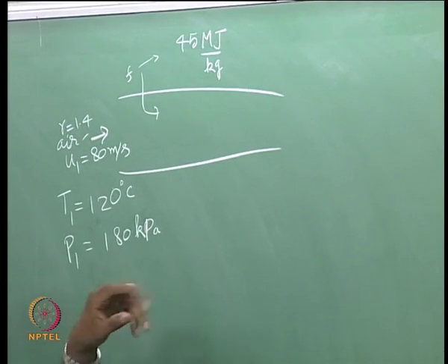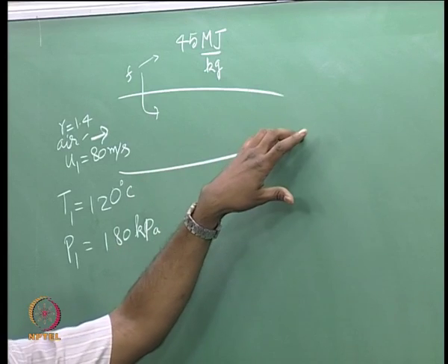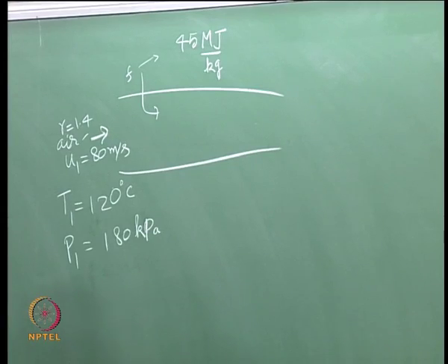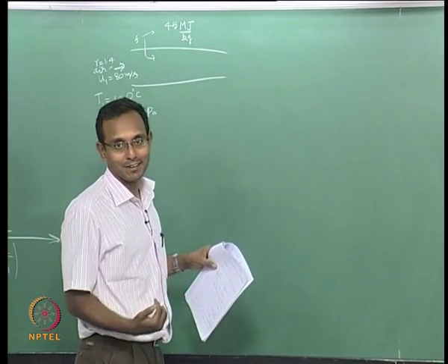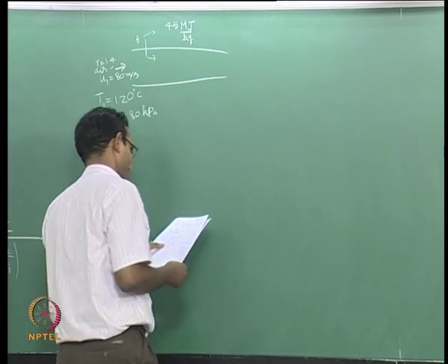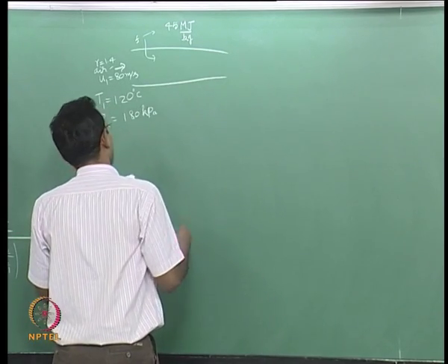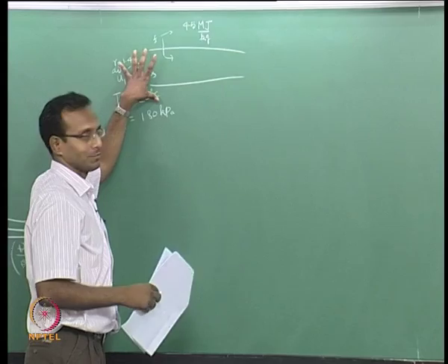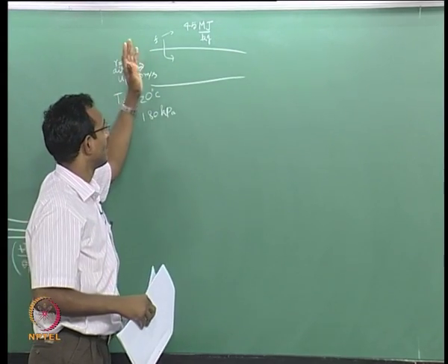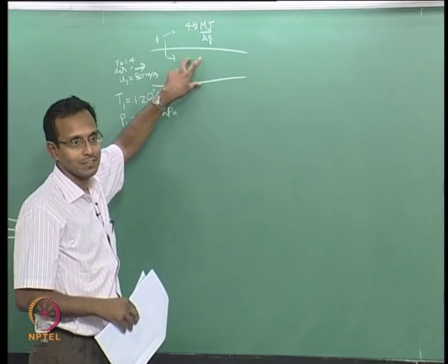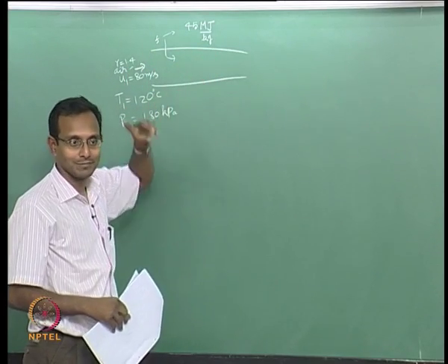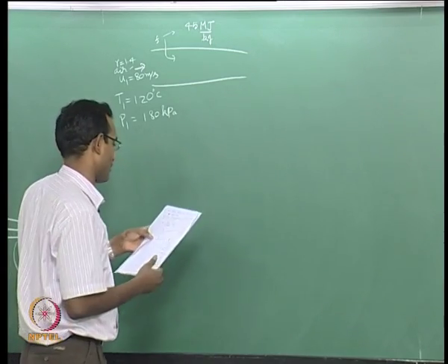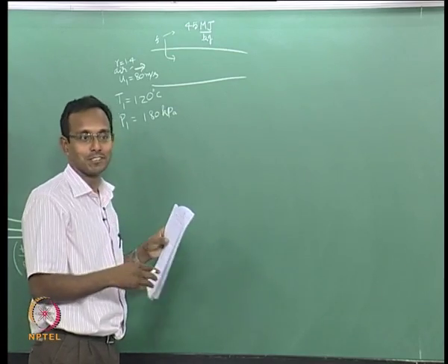And I am going to assume that because of combustion the gamma does not change, as I said in the beginning of the Rayleigh flow assumptions itself. Even though we know carbon dioxide has a different Cp value than air, we will assume that it does not change much. Okay. So we want to find how much fuel I can maximum burn in this particular flow situation. I cannot change the incoming conditions, I want to see how much I can burn inside this. Assume a constant area duct currently. Even though most combustors are not constant area ducts, we will assume a constant area duct for this problem. Then only can I apply all my Rayleigh flow equations here currently.